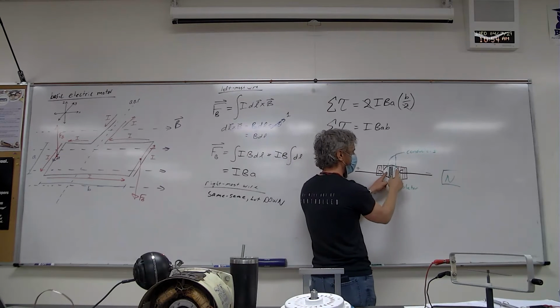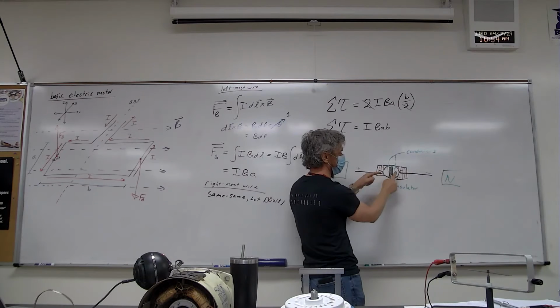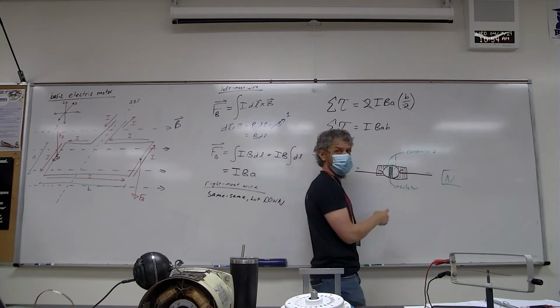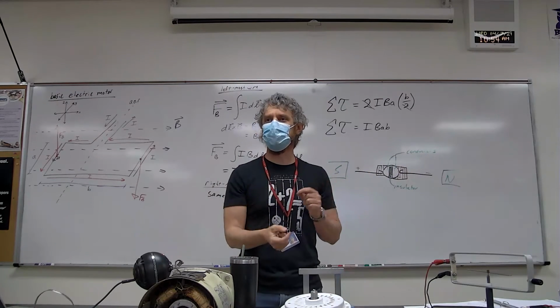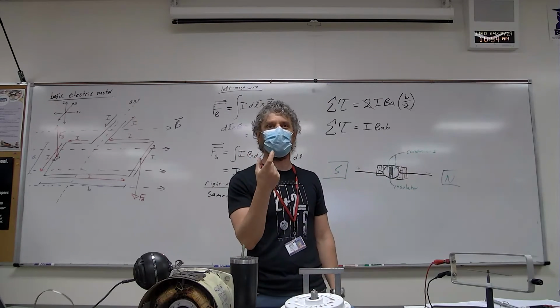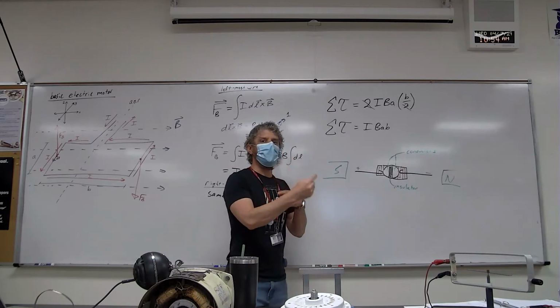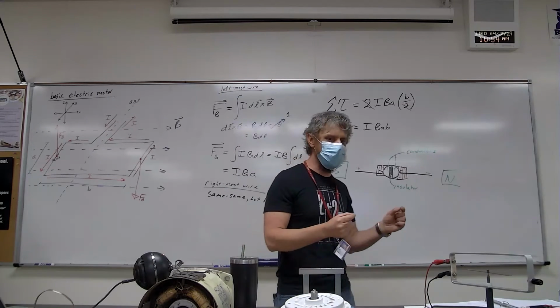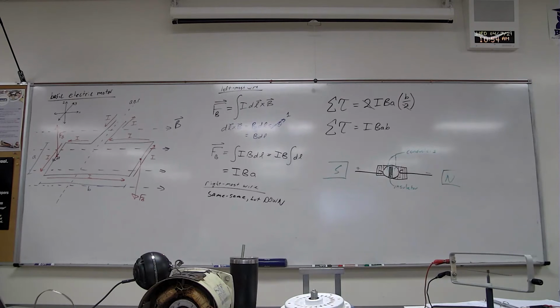So right here, this side is connected to the negative voltage and this side to the positive voltage, but as it rotates through 180 degrees, this one will be connected to positive and this one to negative. So it literally reverses the direction of the current, and reverses the polarity of the magnetic field generated by the piece of iron within the coil wire. And it does so every 180 degrees. Every time it goes through a 180 degree rotation, the current direction switches, and it continues that cycle over and over again.